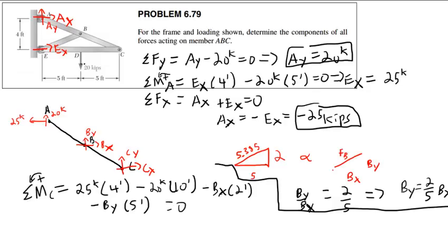Okay, the reason we don't need this 20 kip force is this force is not applied to this member. This force here is not applied to member ABC. It does experience a force from it, but that force is carried through the reaction CY and CX, and through a bit here as well. So we don't need to worry about that. On our balance of moments, we are only including the forces shown on the free body diagram of that member.